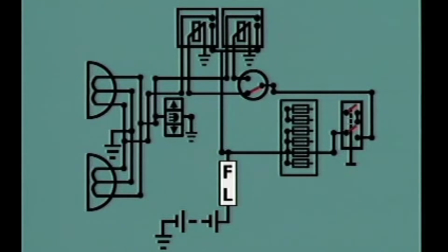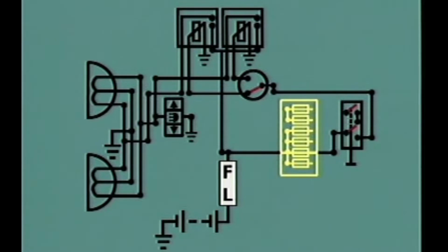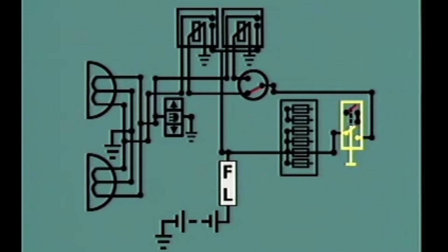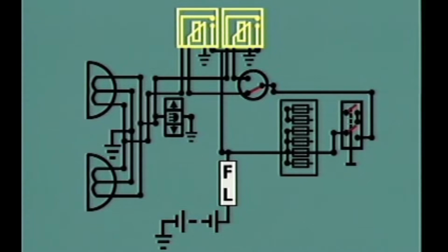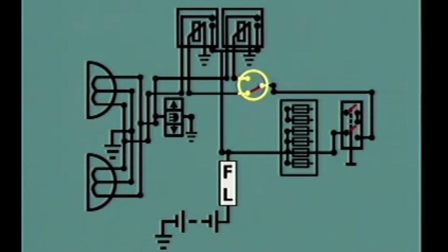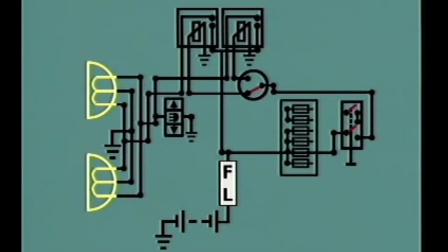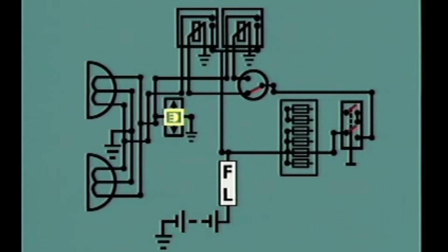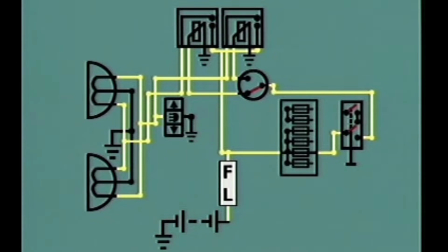The headlight circuit consists of the battery, fusible link and fuses, headlight switch, headlight relays, dipper switch, headlights, high beam indicator light, wiring of a suitable size to carry the electric current through the circuit, and the ground circuit.